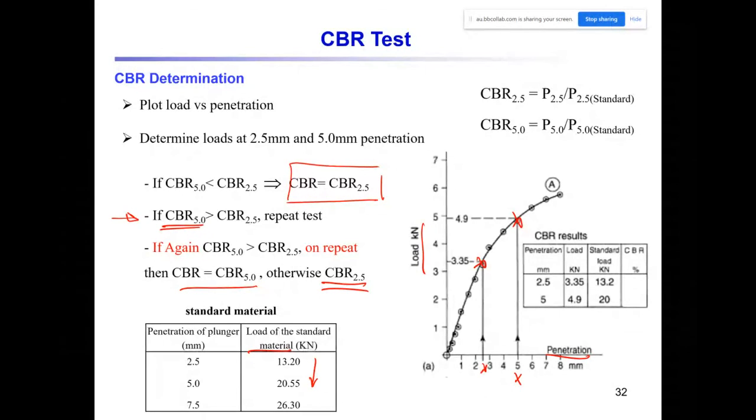So why CBR 5? Okay, I answered that question. What thickness would you consider as small enough to not account for the soil? The thickness depends on your engineering judgment. So generally for 0.2 meter thickness, if the soil is weak, you need to get rid of that layer. But it depends. It depends on the project.